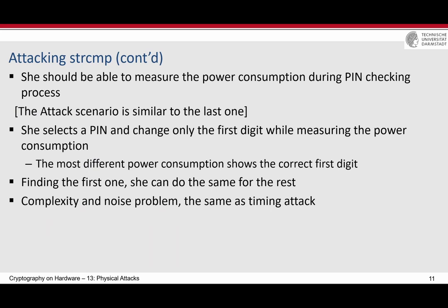The attacker should be able to measure the power consumption during the pin checking process instead of measuring the time. We will see one slide about this: you measure the power consumption over time, and you see exactly at every nanosecond or picosecond what happens inside the device, how much power is taken from the VDD pad.